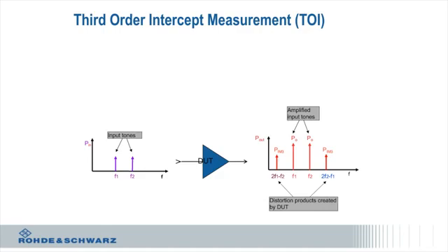They're too close, right? And the closer these two signals get together in frequency, the more challenging it is to get rid of those things. So you need to choose an amplifier with adequate characteristics so that it won't generate noise that you can't process. So this is typically a trade-off.